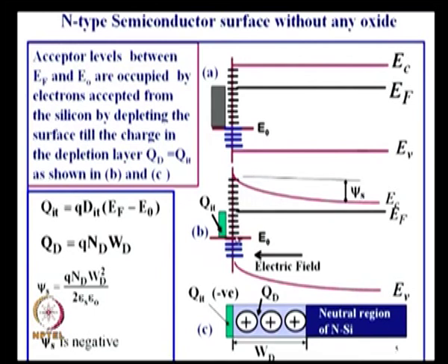So, the distance between the Fermi level and the E_0 has reduced on the surface. So, the band bending is such that charge here is equal to the depletion layer charge. Okay. So, all this discussion is to go into what happens further. This is n type. Please remember, it always moves closer to the neutral level, so that the charge here is equal to the charge in the semiconductor.